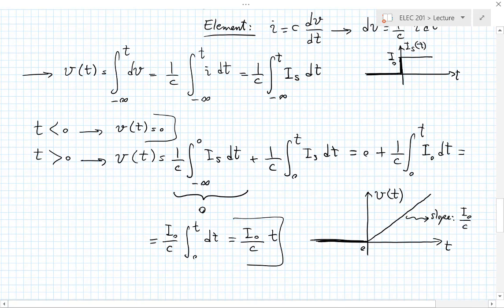So you see, there is no infinity at time 0, but if you give it enough time, it will keep charging up to higher and higher voltages. And that can't be good. It's out of control. So this is, again, a bad circuit from that point of view: if you connect a current source to a capacitor just like that, it will keep charging up. Remember, the charge in the capacitor, Q, was CV. So if V keeps growing, Q is growing.